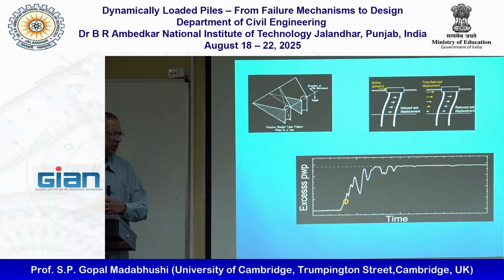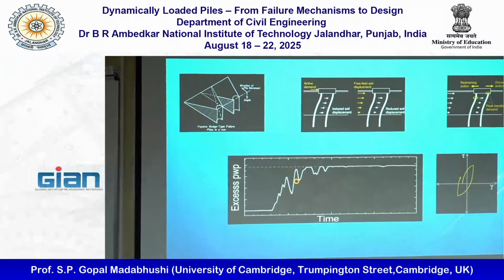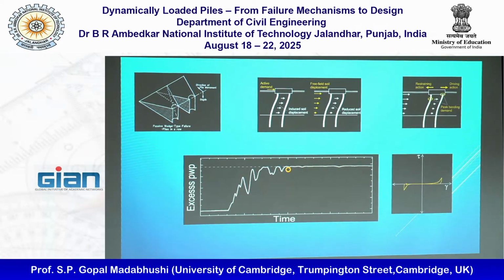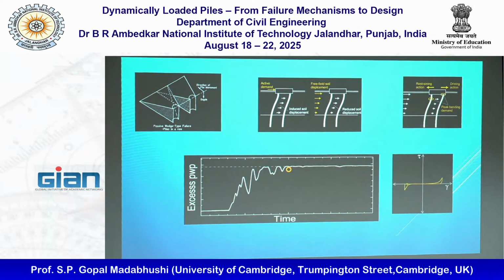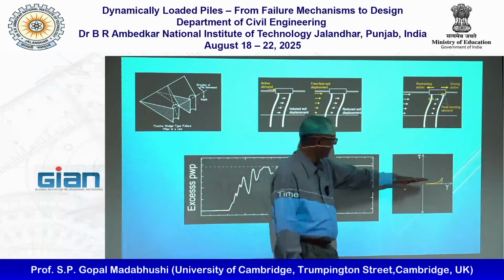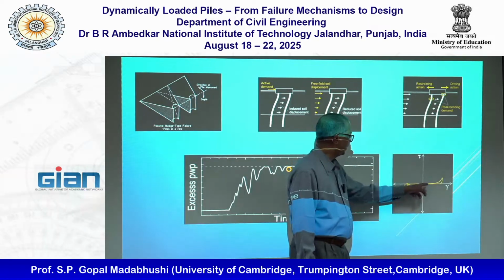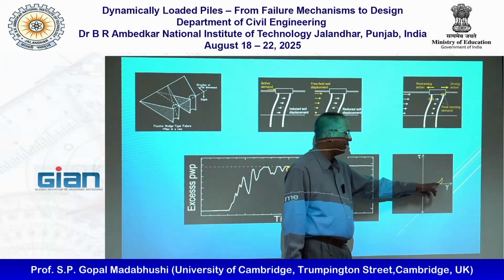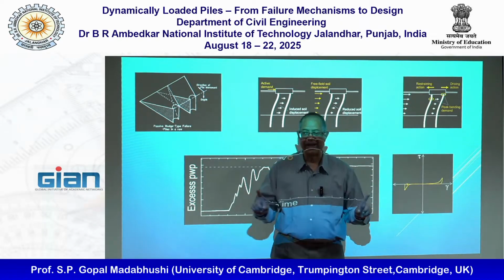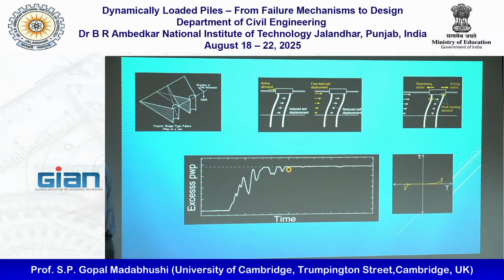I think I showed you this animation already, right? You get an initially stiff response, and as the pore pressure builds up, the tau-gamma loops widen up, and as it goes, they become what they call banana loops, where my tau-gamma response is almost flat, but at extremes, I get dilation to create this stiff response. But for most of the strain range, you get a very soft response.